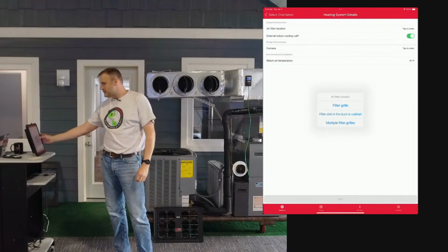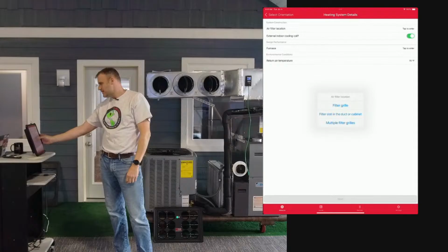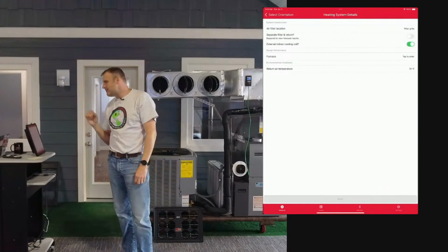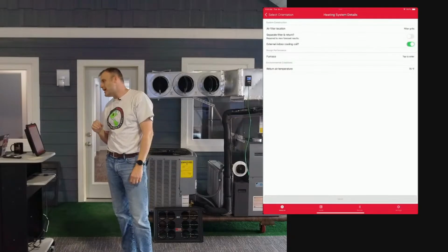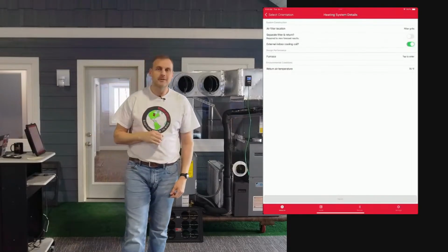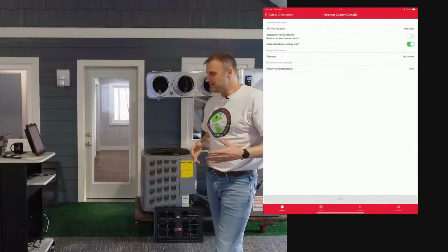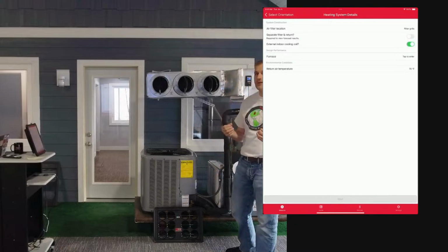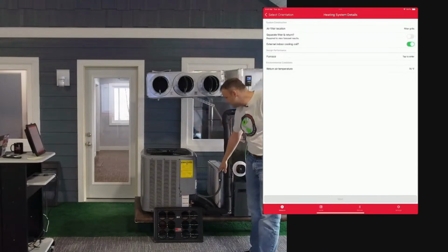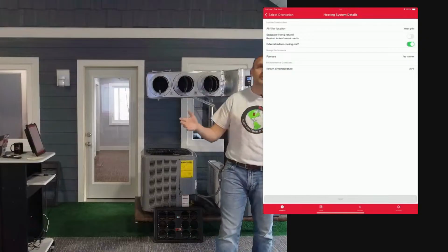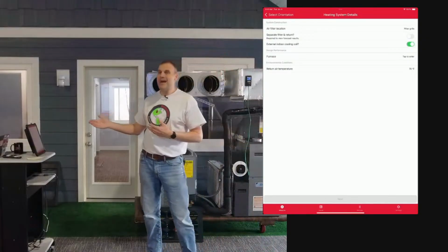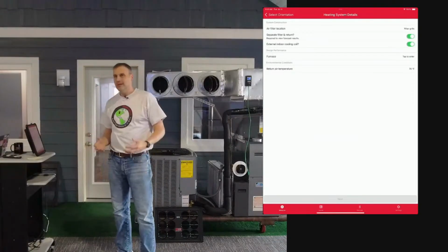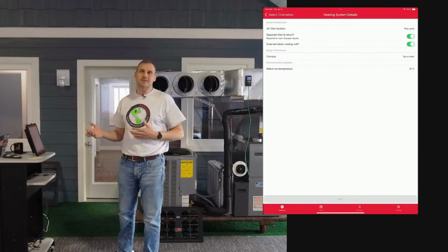The only thing that's changed here quite recently, and I want to make sure I focus on this, is when I select filter grill, watch what happens on the screen. Boom. A drop-down menu just appeared, and it says separate filter and return. It is required to view forecasted results. That is the app telling you this right here. I have a filter grill. When the app originally started, we didn't have forecasting. We had to separate the filter grill from the return ductwork to be able to forecast all of the results. To do that, we had to ask you to give us that pressure mapping part of the sequence. So you have to toggle that on, and we're going to add that pressure measurement to the next screen, which you'll see in a minute.